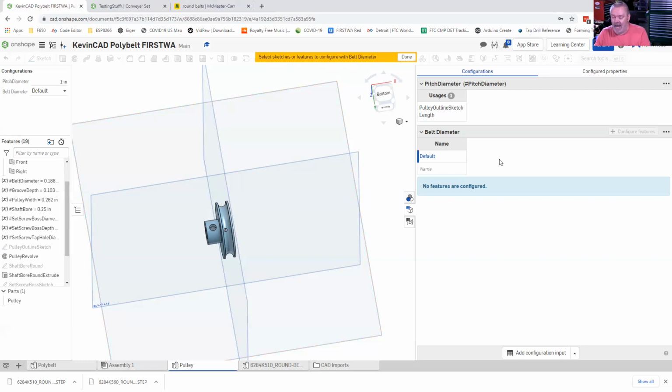What that means is that I can go find anything inside any sketch or any variable to change. It's amazing the flexibility that you have. You can turn features on and off. There's a lot of stuff that you can do. We're going to do the simple one. We're just going to set the value of belt diameter. So I've clicked on this, and there's its property sheet. I want to change the value, and see that the yellow highlighted thing is what's going to get changed. I would like to be able to control the value from my list.